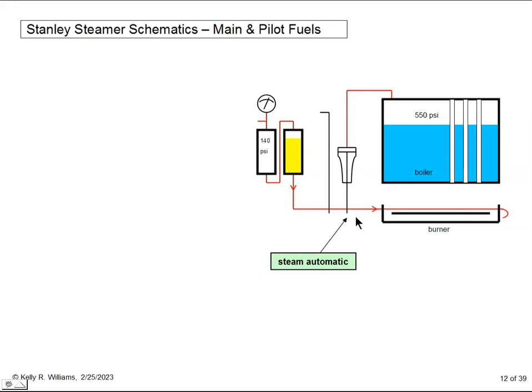Now, we don't ever want to let the boiler run dry. If managed properly with the tools shown in the water system presentation, it will not. But an operator error could result in the boiler becoming empty. This is a bad thing because the burner is so fiercely hot that it can soften the steel of the boiler and allow it to warp under pressure, causing the ends of all of these tubes to leak. Sometimes the boiler can be fixed. More often it has become junk and has to be replaced.